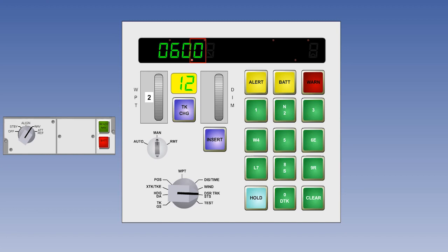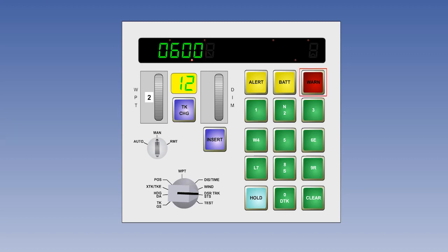However, once nav has been selected on the MSU rotary switch, STS is used to indicate serviceability and for fault diagnosis. If the INS is serviceable, a code, usually 0000, appears in the right-hand LED. Its main use, however, is for fault diagnosis in conjunction with the red WARN light.